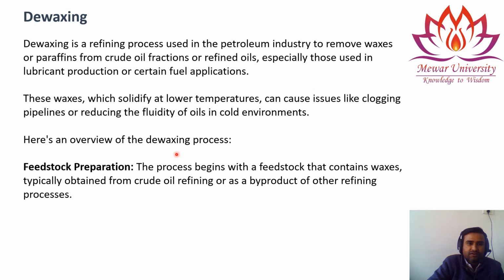Whenever your oil passes through a cold environment, the waxes can cause the flow to stop. It can cause clogging of the pipeline because the wax is very high in viscosity and it deposits in the oil. So it mostly occurs while transporting the crude oil in pipelines.